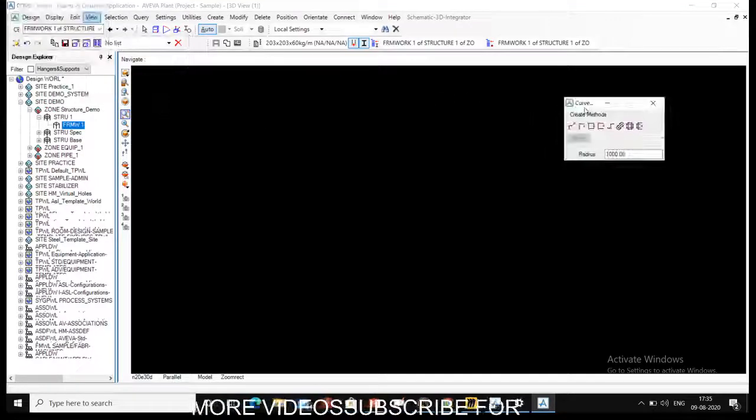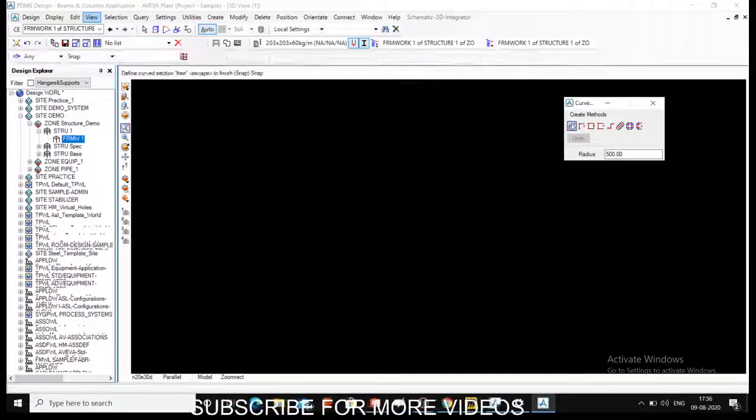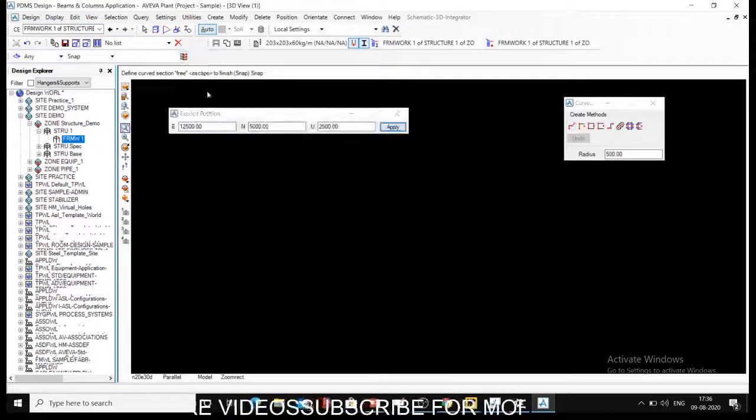Now when you go to curved section, there are various options available with which you can get the curved sections. We will see them one by one. Radius is basically the fillet between two sections, so I am keeping it 500 for now, and we can check with the first option. The first option is your explicit option, where you need a minimum of 3 points to create the curved section.